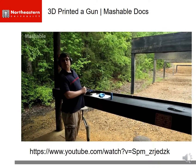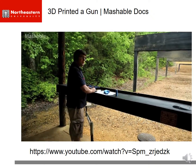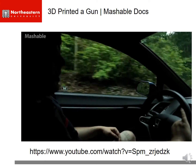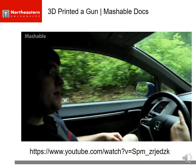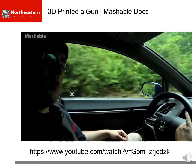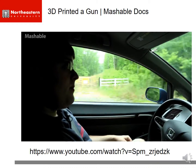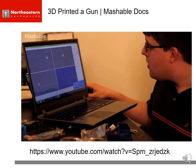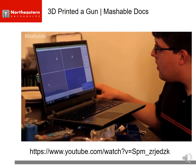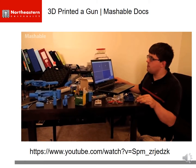It is not firing, so I think I'm done with it. All right, good. So you're done, right? Yes. All right, good. Thanks. All right, we tried it a few times. It was dinging the primer, but it's not going off. It looks like the primer is not taking enough force to actually explode reliably. So I think I'm going to improve the firing mechanism and replace it with a more traditional cylinder striking pin. All right, it should be the basic shape.